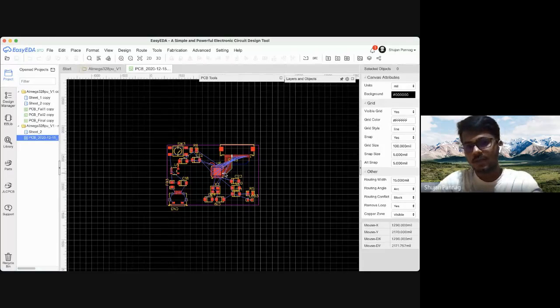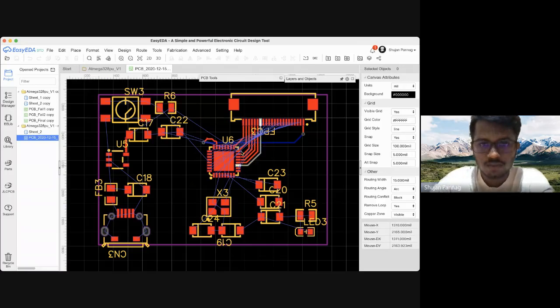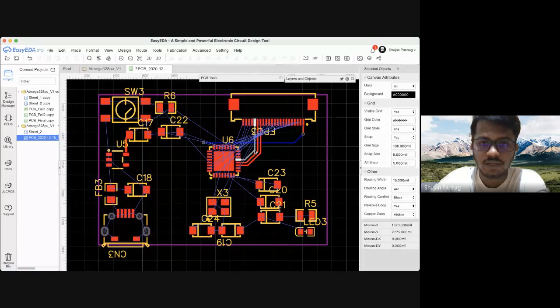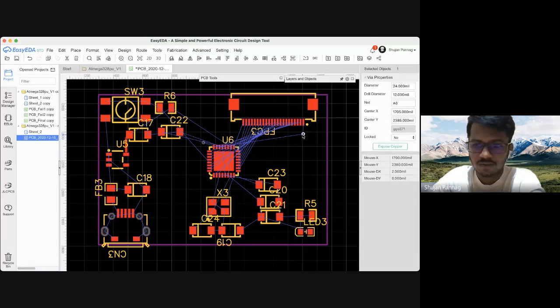But when it comes to microcontrollers, when you have a lot of components, and when it's SMDs, and this space is literally just 4.5 centimeters by 2.5 centimeters, that can be really difficult to do. So I've just done it freehand. I'll just go ahead and delete all this. The placing, I'll show how many iterations it took me to find an appropriate one, because every time you do it, you don't get the same output, and sometimes we really suck at placing it properly.